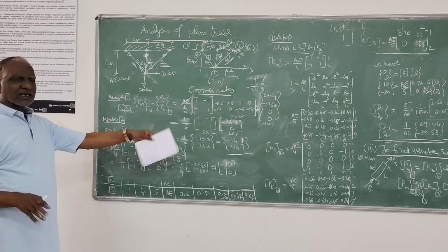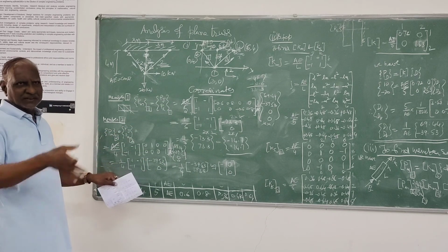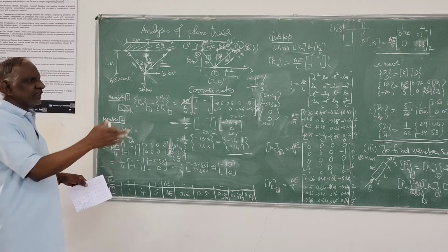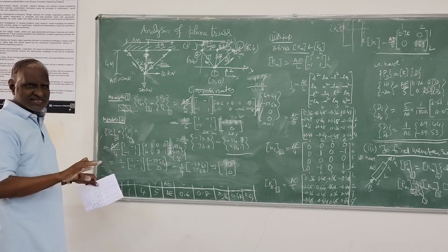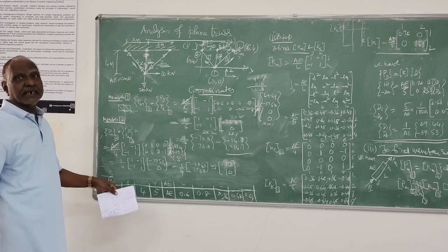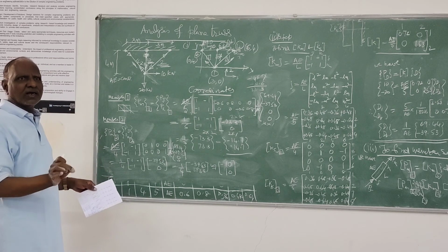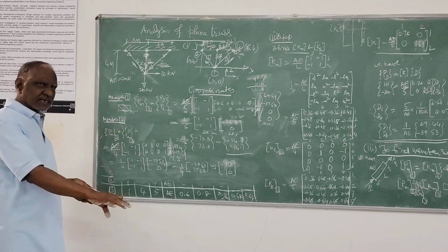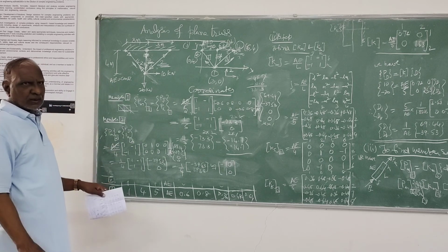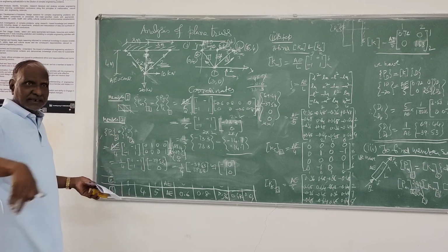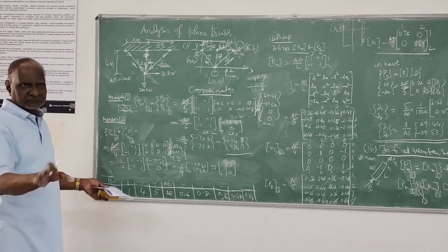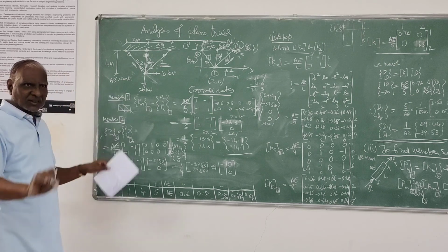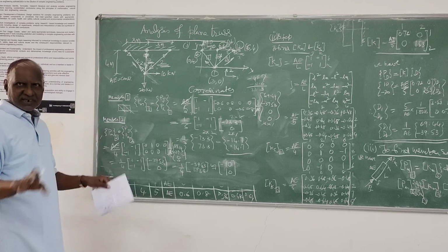Whenever you have inclined members, all the members will not coincide with our orthogonal coordinate system. So we cannot follow the system approach that easily. It will be a tedious calculation, not fast for hand computation. So for hand computation, system approach is easy only if it is orthogonal. Otherwise, that's why we didn't work any inclined frame problem also there. That's the reason why they are clearly mentioned orthogonal in the syllabus. System approach, that's the reason.